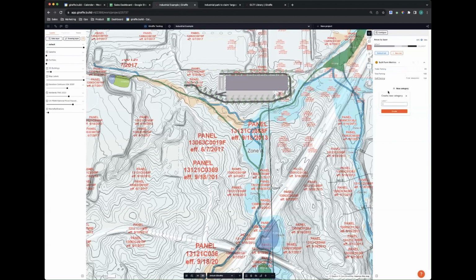I'm going to add a whole new calculation here, and we'll call this detention metrics. Now, for those of you who've done detention before, you'll know that detention is a factor of the amount of hardscape or impervious surfaces that we have covering the site. Usually it's something like area of impervious surfaces multiplied by a coefficient that the county or the state mandates. That equals your volume of retention that you have to calculate or you have to provide on the site.